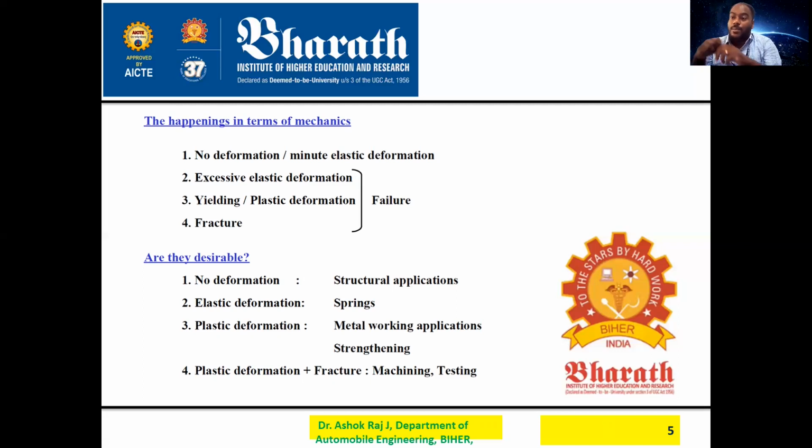But if you take an aluminum wire and play with it, and why am I telling aluminum wire? Because aluminum is a softer material than the other materials. Even copper you can play with. But with aluminum wire, while playing you can see the deformation, and once you leave it, it never comes back to the original position. That is called plastic deformation. But in between, from elastic to plastic deformation, that region is called the yield point, and they also call it the transition point.